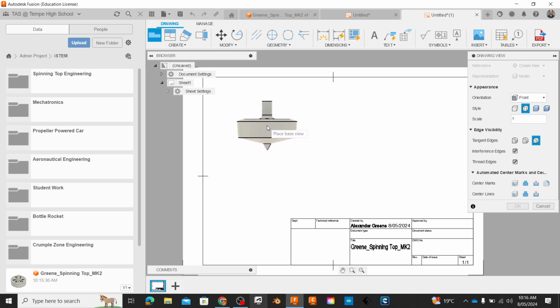This is our A4 sheet, and we're going to lay our front view here. Now, do I have to lay 3 views, a top, front, and side view? Who knows? Would I do a top, front, and side view, or would I just do 2 of those? Top, front, and side. Why would I do top and front, or top and side? They're the same thing. Why? Because it's a cylindrical object. Okay? Thanks, Axel. So I'm going to lay that one down there.